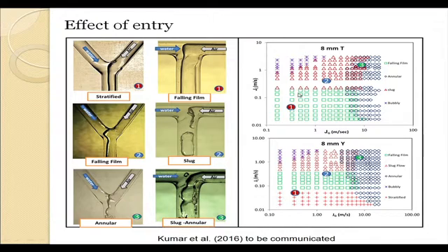So this flow pattern map shows that while falling film exists over a large range for a T junction, a considerable portion of this area is occupied by the stratified flow. Now, we operate at a higher velocity. What happens? The moment we go to a higher velocity, there is a pinching action of the water, as is evident here, and the gas cannot flow as a single core. On the contrary, the liquid tends to pinch the air and break it down into periodic slugs, and the slug flow pattern emerges. And this is evident from the flow pattern map.